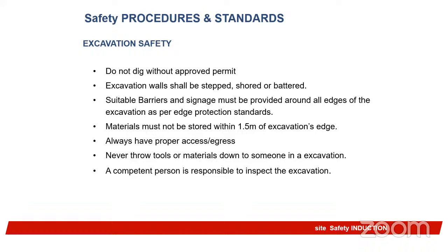Always have proper access and egress, which is very important. Never throw tools or material down to someone in the excavation. A competent person is responsible to inspect the excavation at all times.